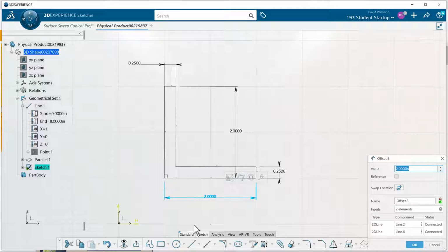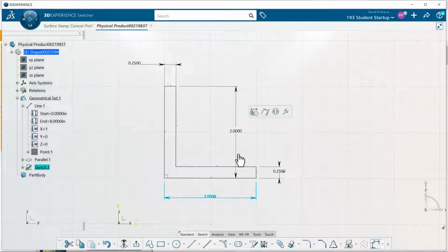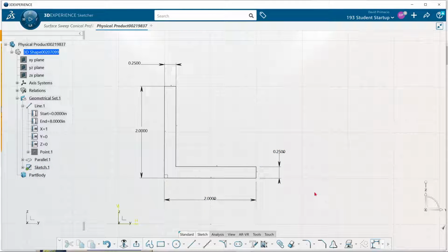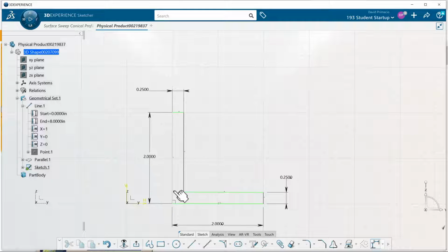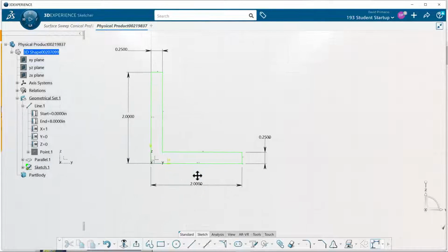And I'll go equals and equal this one. And as a good habit, you should pull these off a 1/2 inch from the part, so that we've got a nice clean part where the numbers are visible, easy to see. Someone else working on it can work on it. And what you want to do is lock it to this axis. So you contact the bottom to the horizontal, contact the vertical, and it's fully constrained. I can exit out,